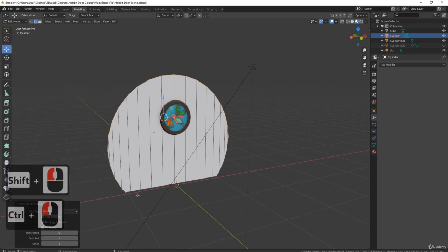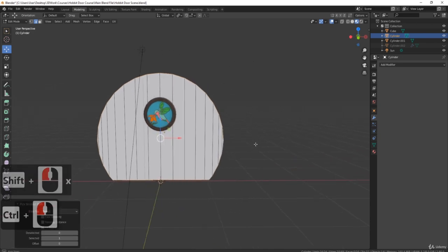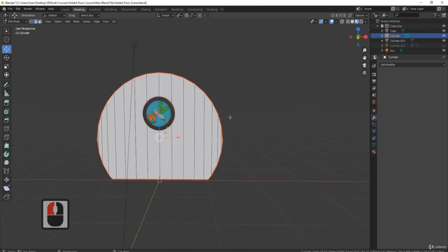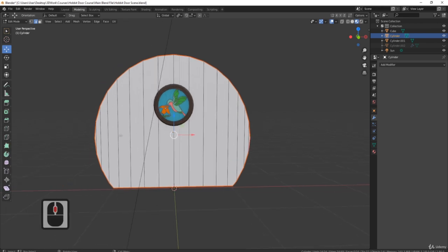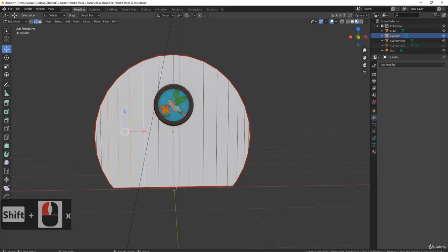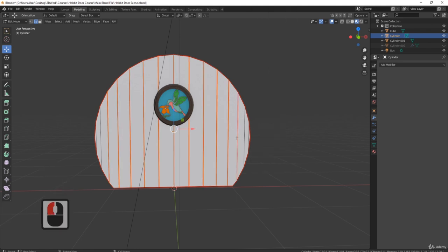So I'm going to come round all the outside of here, including these. I'm going to grab it all the way up to here with control click. I'm going to right click then and mark seam. Now I need to think where the actual panels are going to be for this. So I think I'm going to have one here, and then it's just going to be every one going across. And then I'm going to use these two here just as one piece of wood. So I'm going to right click, mark seam. Now you should end up with something like this.